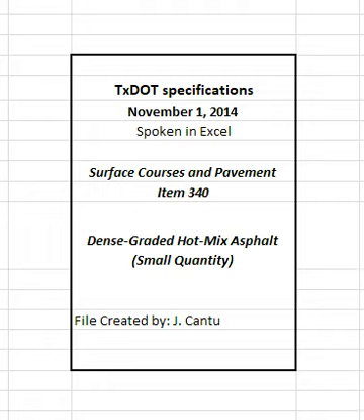The maximum allowable time for the engineer to exchange test data with the contractor is as given in Table 7 unless otherwise approved. The engineer will immediately report to the contractor any test result that requires suspension of production or placement or that fails to meet the specification requirements. Subsequent mix placed after test results are available to the contractor, which require suspension of operations, may be considered unauthorized work. Unauthorized work will be accepted or rejected at the discretion of the engineer in accordance with Article 5.3, Conformity with Plans, Specifications, and Special Provisions.